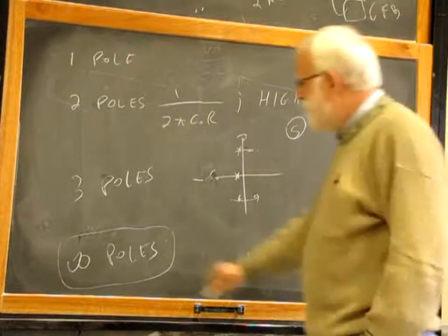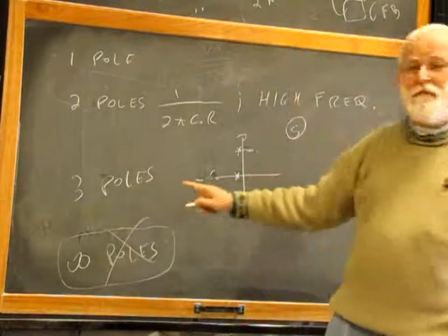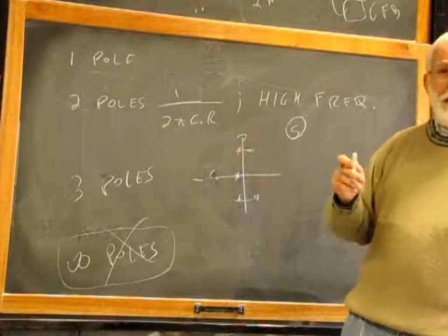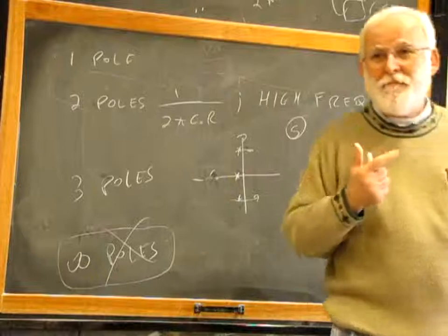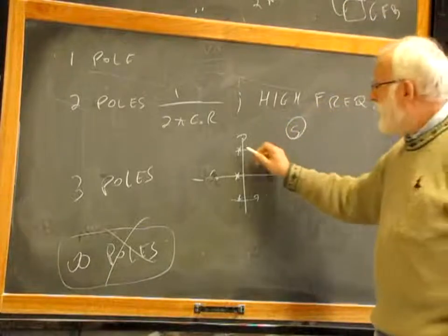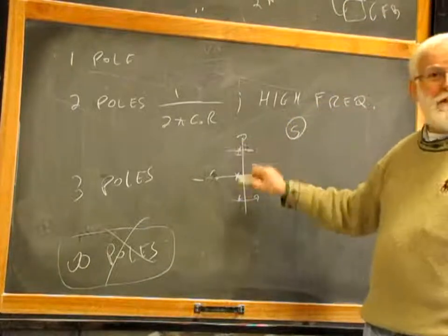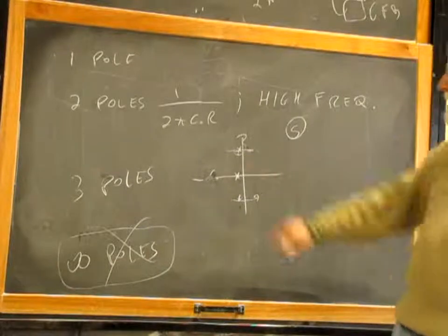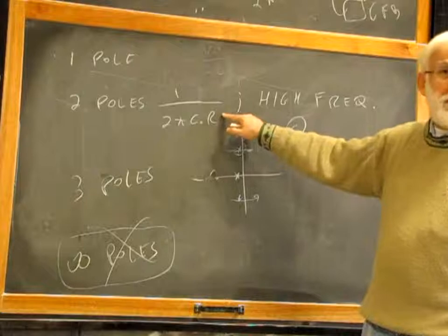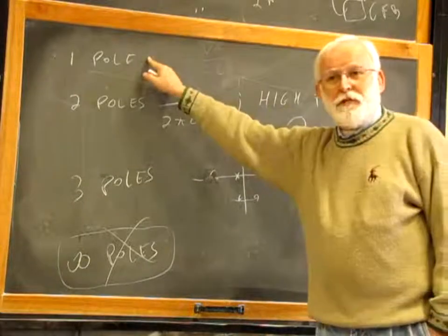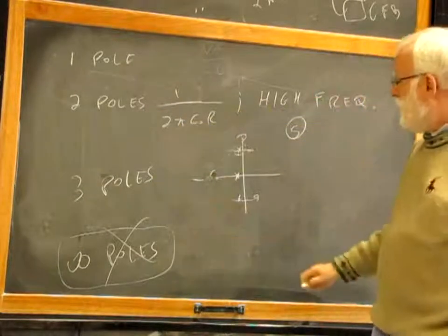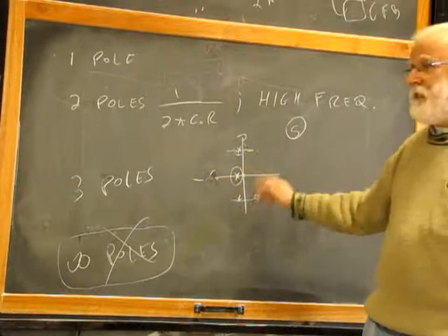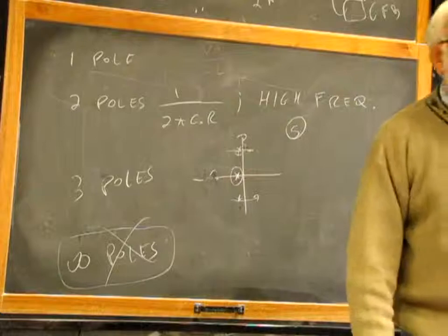Don't worry about this. This is a good idea because this tells you that you have instability, and these two poles have a Q that depends on duty cycle and the compensation length. So you can add a compensation length that keeps them to the left, far away from the imaginary axis. This is basically useless because we don't need it, and this is what we use. Even if we use the three-pole model, this is the important one. And then you have to keep this on the left-hand side. Okay?